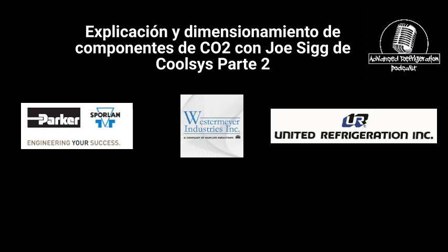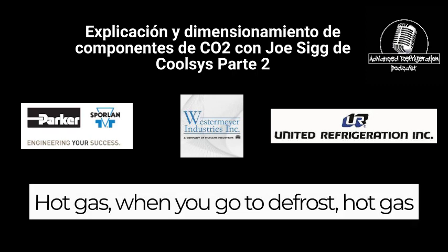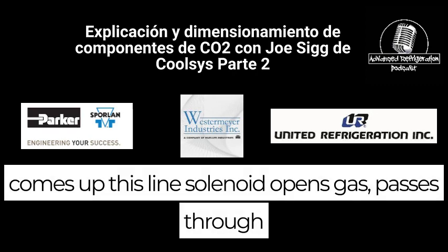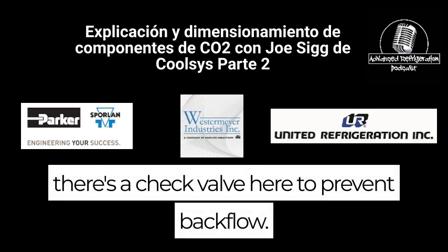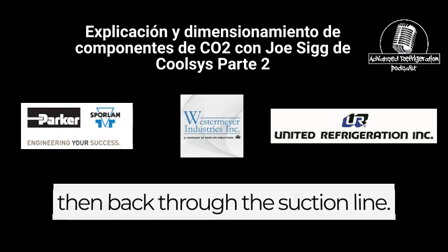So that's basically where we're at. When you go to defrost, hot gas comes up this line, the hot gas solenoid opens, and gas passes through the drain pan first. There's a check valve here to prevent backflow. It goes up through the coil and then back through the suction line.